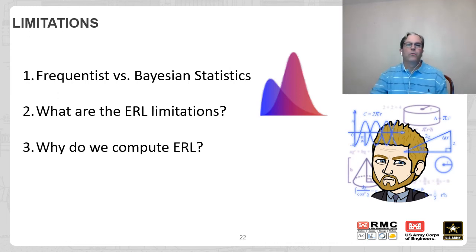The main reason we need to do this is because the current version of RMC RFA and many other similar stochastic flood hazard models use effective record length as the input parameter to model the uncertainty in the frequency curve. A primary objective of the process we are doing is to make sure that the effective record length we select gives us good and consistent results between the RMC RFA analysis and the frequency curve that we computed in RMC Best Fit.